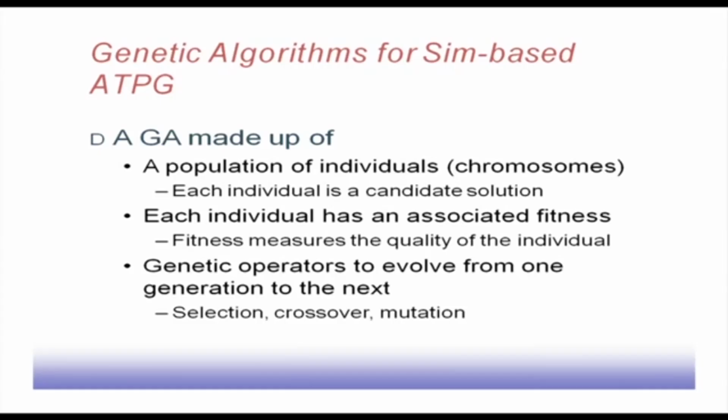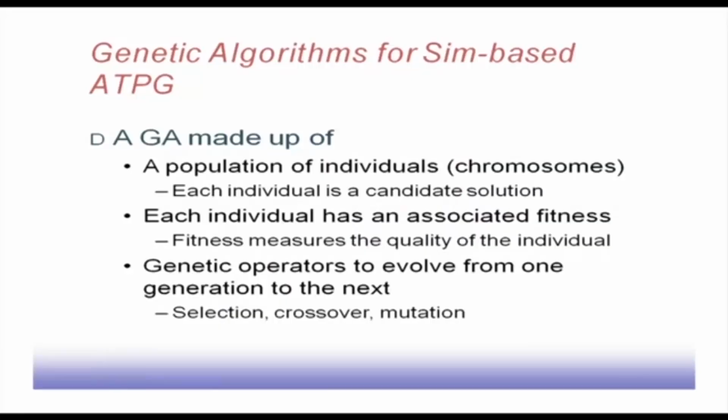But if you ask me to give any test pattern, I can give it very easily. I can just give any random 0 1 binary sequence to the inputs of the circuit. That itself is a test pattern, and hopefully it will detect at least some faults. So, each individual is a candidate solution, and I can give a large number of such individual solutions without bothering about their quality. After that, each individual has an associated fitness.